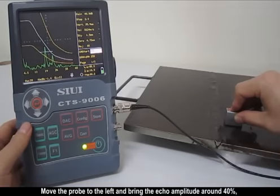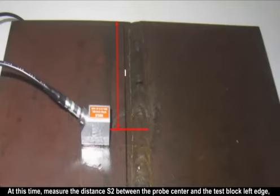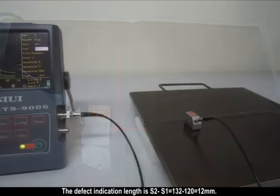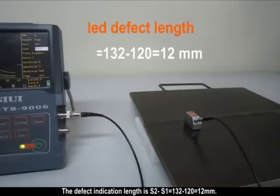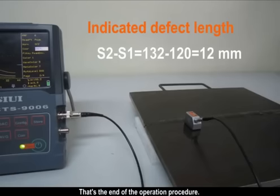Move the probe to the left and bring the echo amplitude around 40%. At this time, measure the distance S2 between the probe center and the test block left edge, for example, 132 mm. The defect indication length is S2 minus S1, which is 132 minus 120, equals 12 mm.